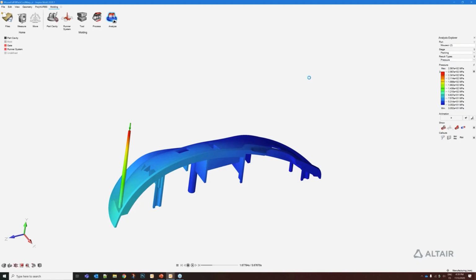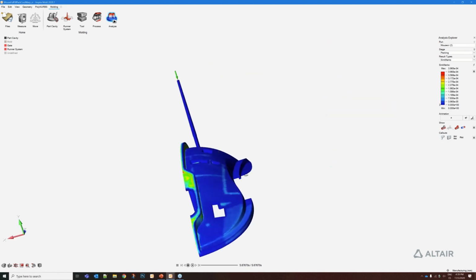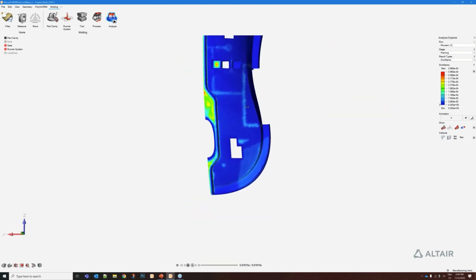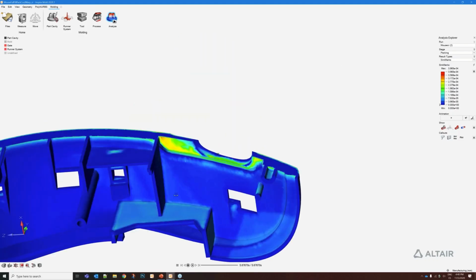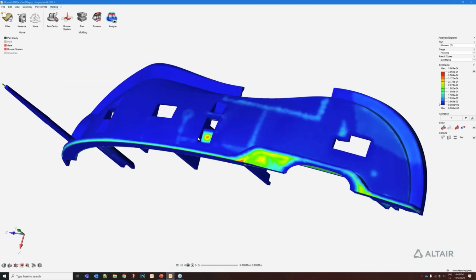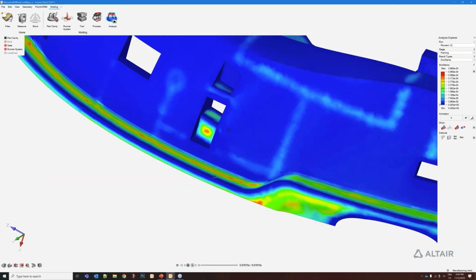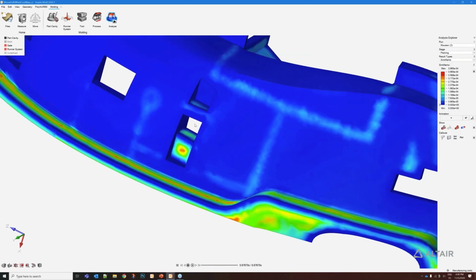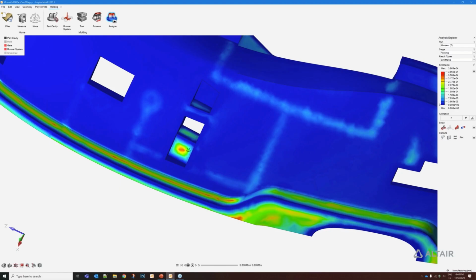We can predict sink marks that will be generated during the packing. So you can see how the ribs in the background are creating some sink marks on the skin of the part, and you can detect really deep or critical sink marks. These sink marks are probably because of the highest thickness that we have in this particular region.